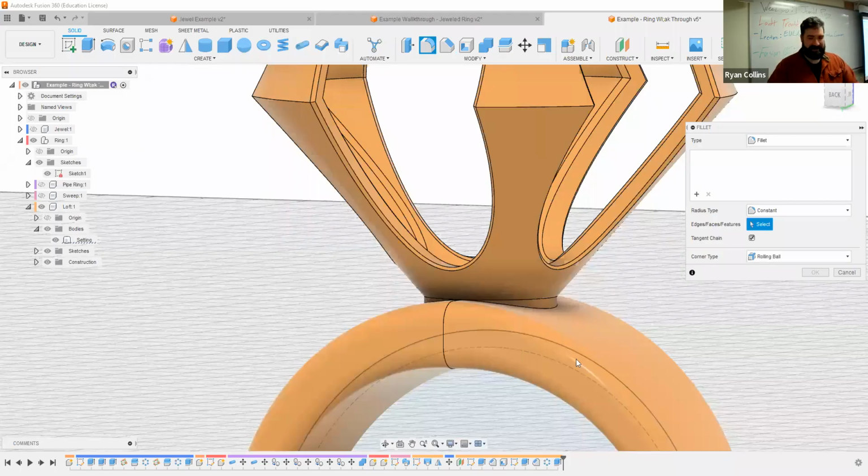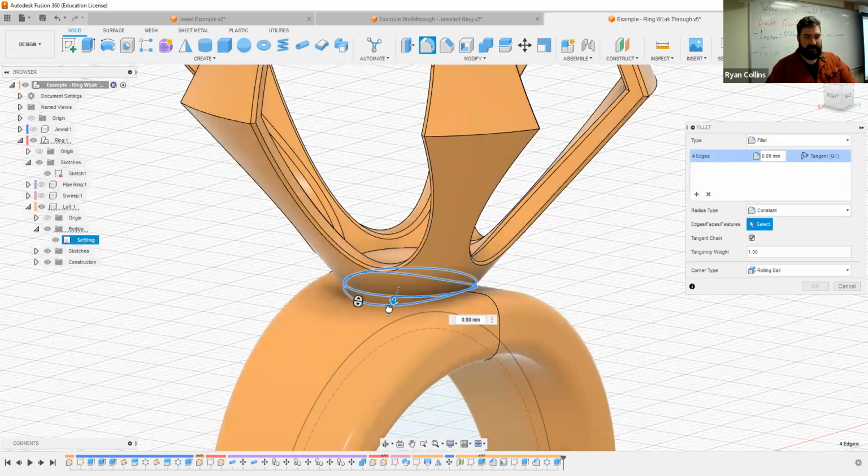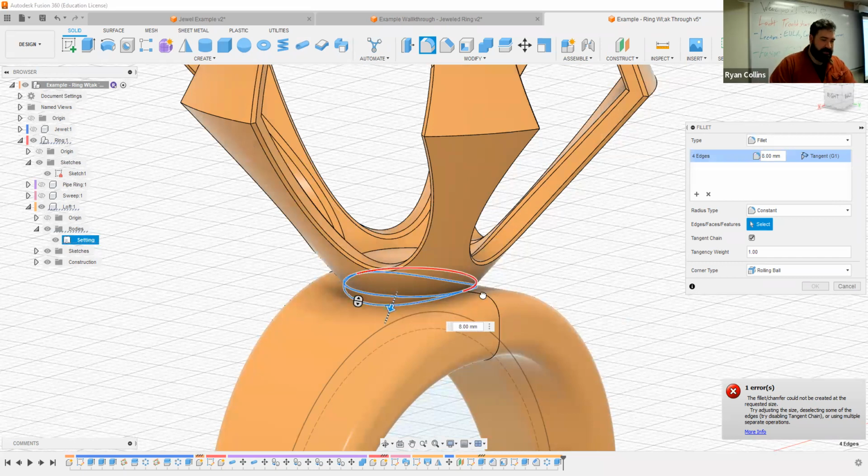Okay, computer saved. The issue was that I selected the faces. What you should do instead is select the actual edges. That should help. Yes, it does make a distinction. There we go. So don't go too far with it. Honestly, I have found that if you use the slider, it can kind of go way wonky before you realize what's happening. So I would enter these values numerically.